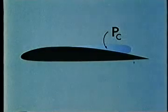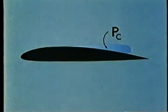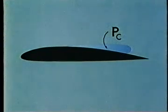The cavitation number at which inception of cavitation takes place is called the critical cavitation number. Above the critical cavitation number, no cavitation occurs. Below the critical, it does occur. Operation with a cavitation number well below the critical produces a very large cavitated region. In two-phase, one-component flow, the cavity pressure is just the vapor pressure. In a multi-component flow, the cavity pressure is the sum of the partial pressures of the vapor of the liquid and of any gases that may have been introduced into the cavity.